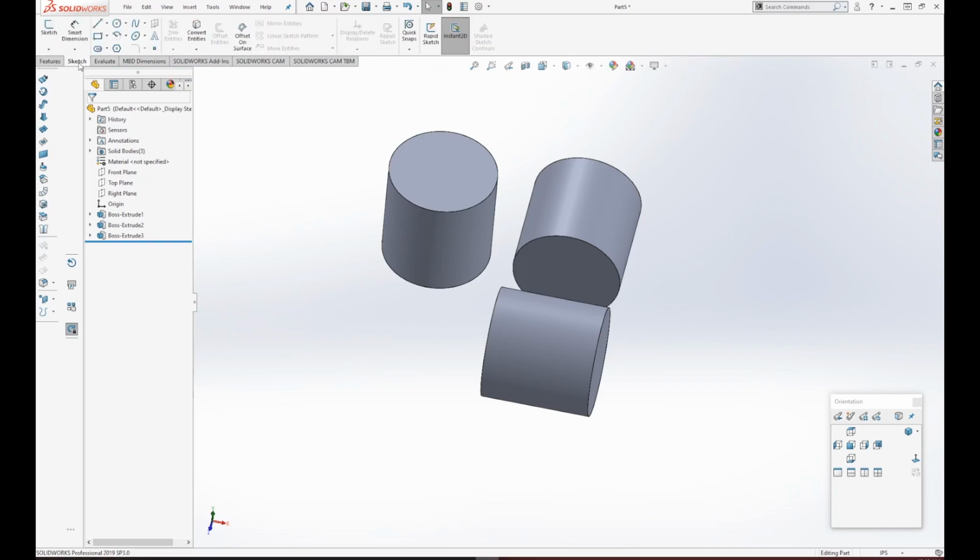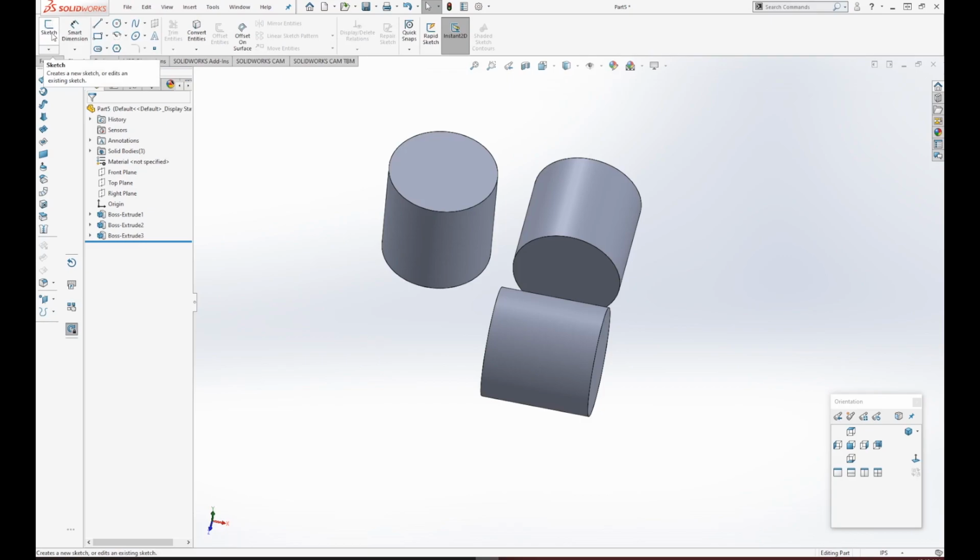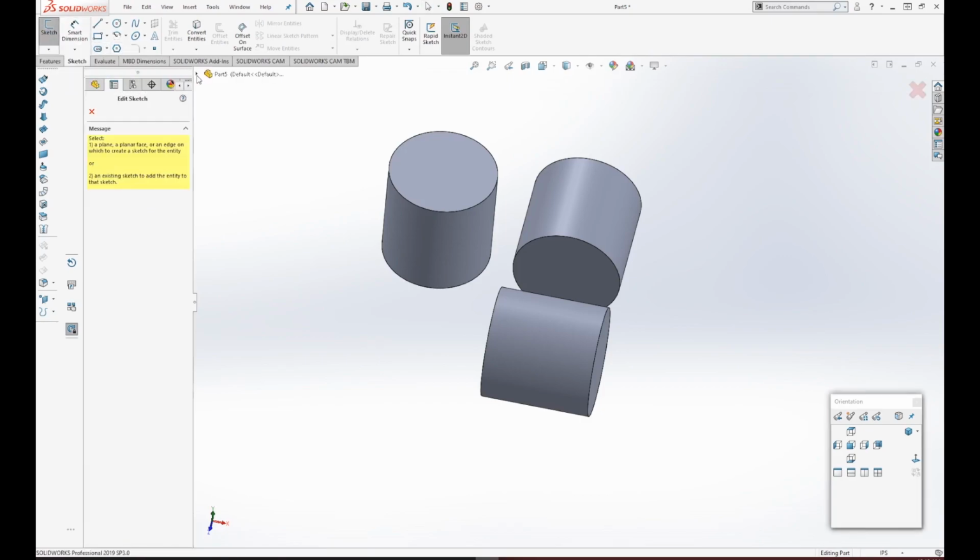Whatever you're building, get it into the right direction. Okay, so let me go ahead and continue on by showing you guys some more things. Enter back into sketch mode by clicking the sketch tab, clicking the sketch button. Go ahead and select your front plane.